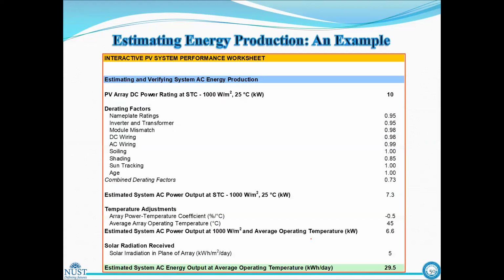So finally, we know all the critical parameters. To design the system, we can start from photovoltaic modules in case of an interactive inverter. So the photovoltaic array can have some particular device rating. So starting from that nameplate, we know 0.9% will be degraded. Okay, so just considering the nameplate rating, and then besides this, we should also consider some other derating factors.